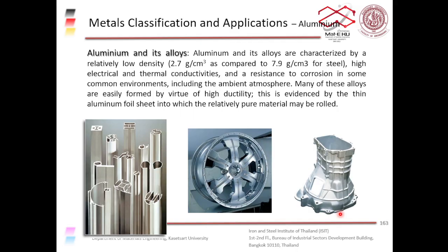That means you have fewer pylons to construct, therefore you save money. So in the long run, aluminum construction won out. The conductivity of aluminum is not that far behind copper, so you use aluminum not just in the power line, but in the substation, in the bus bar, etc.